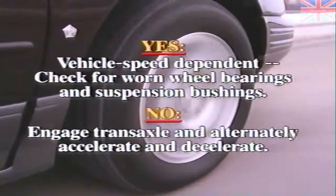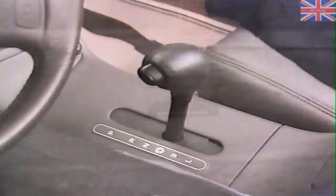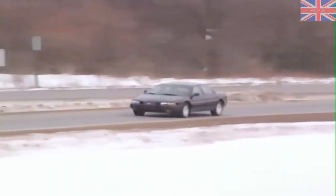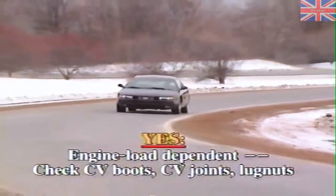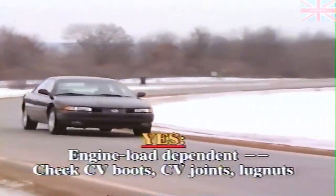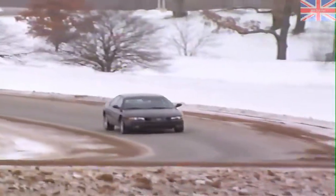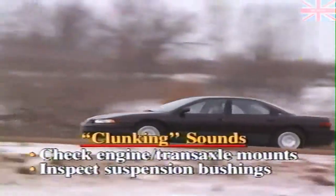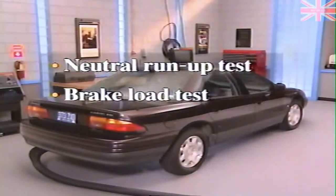If noise or vibration are not generated while coasting with the car in neutral, engage the transaxle and alternately accelerate and decelerate while making sweeping turns. If noise or vibration now occur, the problem is dependent upon engine load. Check for damaged CV boots, worn CV joints, and look for loose or missing lug nuts. If you hear a clunking sound when you quickly accelerate or decelerate, check for worn engine and transaxle mounts and inspect the suspension bushings.